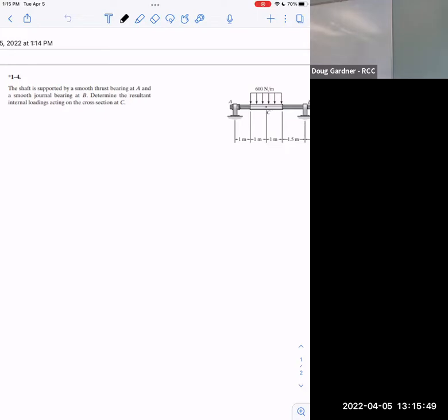But what it does is, if you do want to spin something and you want to keep it in place, like if I try to spin this pencil, it's flying out of control, right? I don't want it to fly out of control. I want it to stay right there. So I kind of squeeze it right here. But notice it can move left and right. There's nothing stopping that. So do you see how it says there's only one resisting force there? It's vertical for a journal bearing.